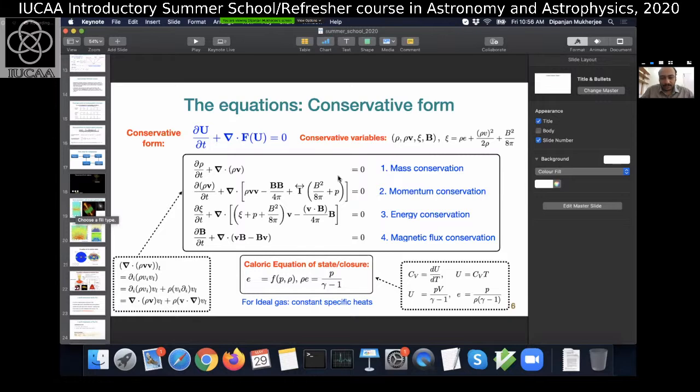That is right. Well, volumes also have a discreteness in the solution, but if you have differentials in strong discontinuities, the derivative blows up, right? So if you have a shock in a system, or a sharp change or sharp gradients in your fluid variables, then the differential system will have an extremely high value of the differentials. In that case, what people do with the differential equation is add artificial viscosity to reduce the gradient of the fluid variables. But this artificial viscosity adds extra dissipation in your system, which is unphysical. This problem does not arise in the Godunov scheme.